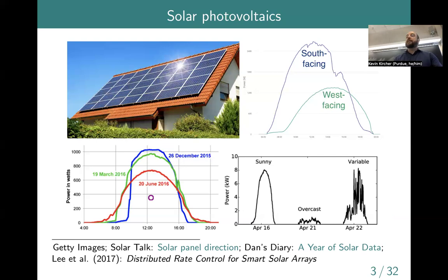Yes, I think so. Right. So typical guidance for a solar array, the ideal solar array in the northern hemisphere, is to point it south and then to tilt it at an angle that's equal to the latitude. So we're at, I think, about 40 or 42 degrees latitude. So we'd want to tilt it about like that. So for an array that's tilted more at that kind of optimal orientation, we probably would see that the clear sky envelope for summer, the red curve, would be above the blue curve here, or a similar height. Does that make sense? Cool.